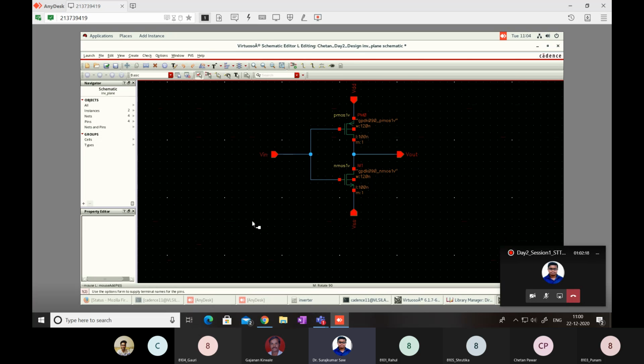Rahul, are you able to see, right? Yes, sir. Okay, fine, very good. See, now again I'm checking. Whenever I do a correction, I will go for check and save. Now I want a supply voltage in this circuit. So we will provide a supply voltage. I have just copied this VDD by using the C command. Copy that VDD and copy the ground here, and I will provide one supply voltage here like VDC.